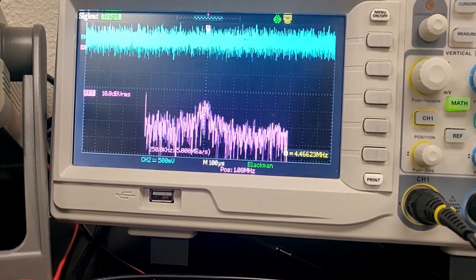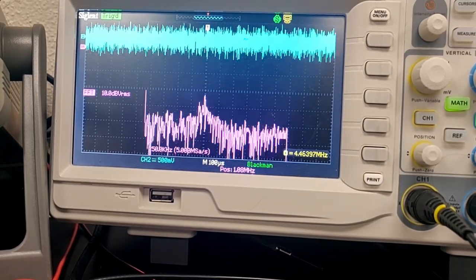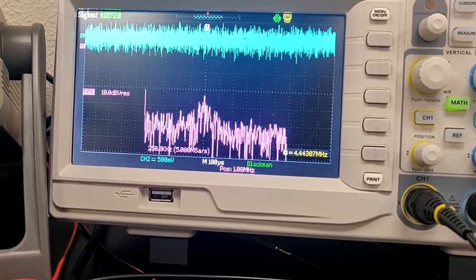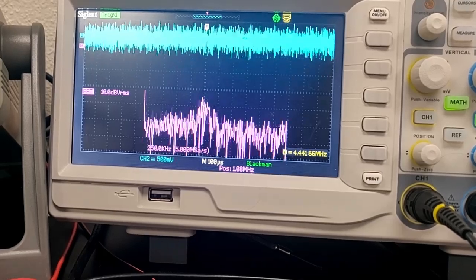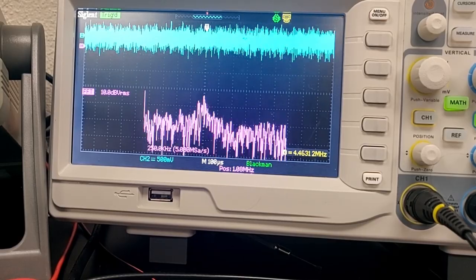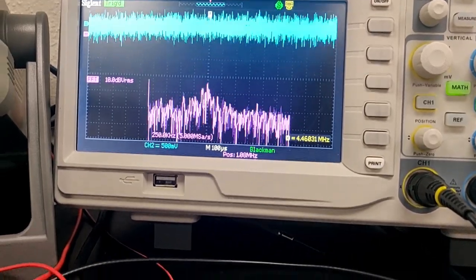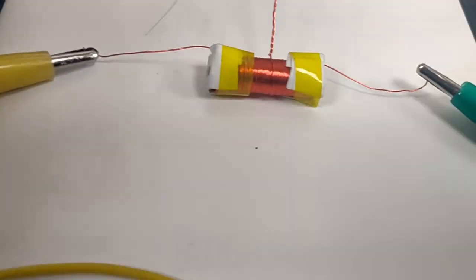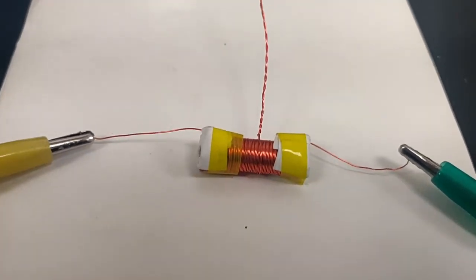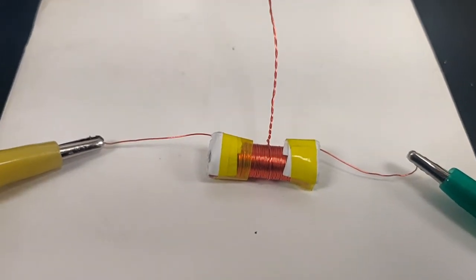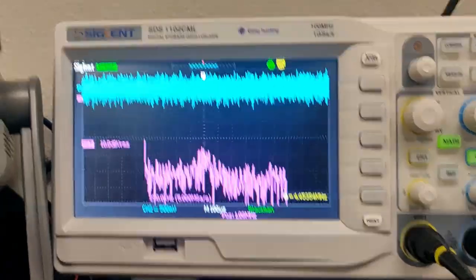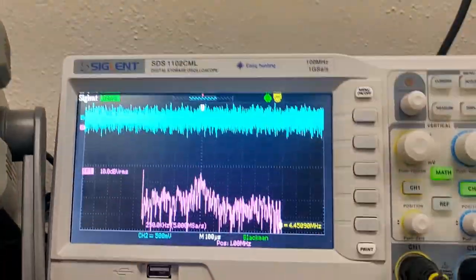And just to comment on the components for our circuit, the capacitor is a variable capacitor. Right now I have it set to its minimum value, so it's right around 60 picofarads. And as you can see, I'm measuring the total. I have the lead set up for the full width of our inductor, so we're getting the maximum possible inductance for our inductor.